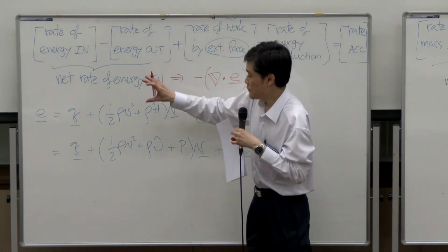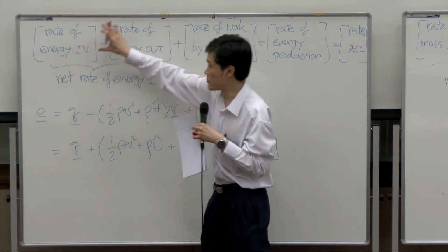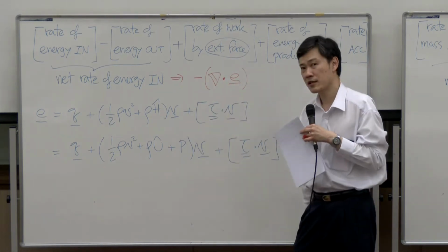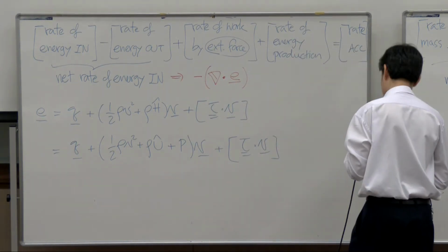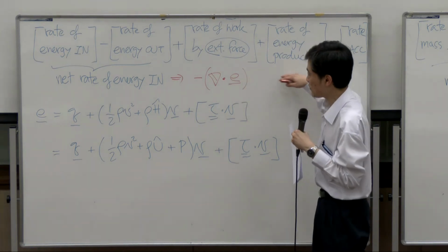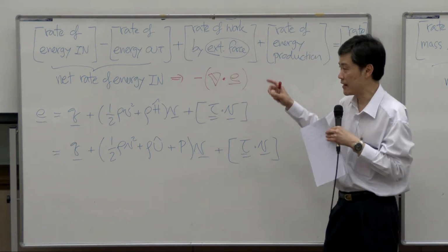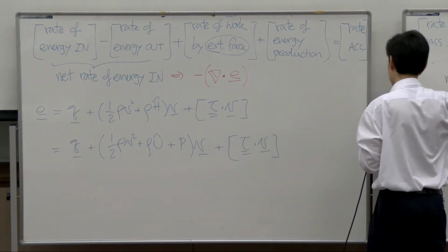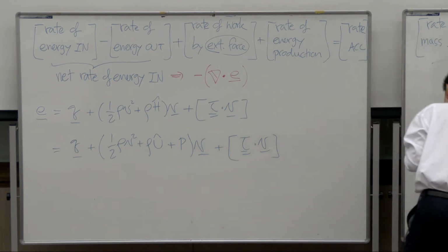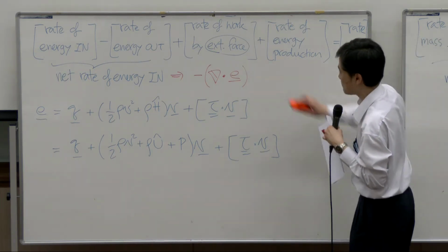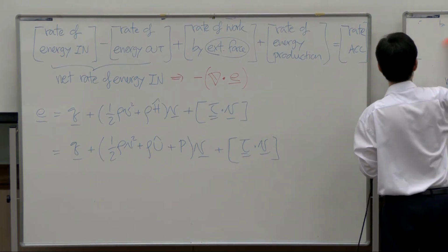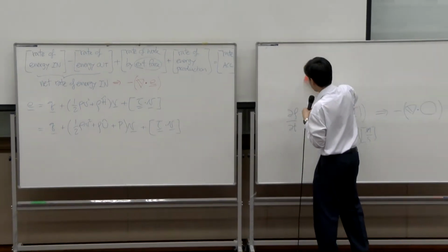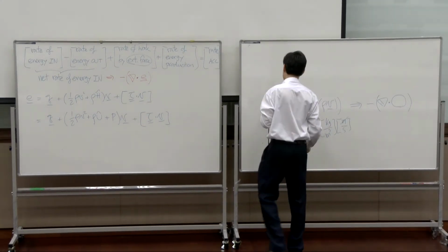And if you take fluxes going in subtracted by fluxes going out, you will end up with this form of equation, just like whatever we derived in mass. Of course, in detail, you can start deriving from shell balance and reduce the size of shell in the same manner as what we did from mass balance, but it would be very complicated, so I figure that if I explain it like this, it would be easier to understand. All right, the key is net flux is represented by minus del dot that flux.